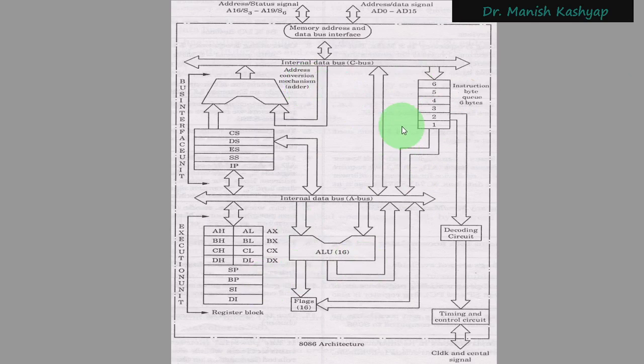So the fetch, decode, and execute, these three phases of the cycle, are independent of each other. Otherwise, in 8085, what used to happen was we would take one byte from the externally interfaced memory, keep it in the instruction register, decode it, and then execute it. Then we take the next byte, etc. But here we try to fetch 6 bytes at max in advance.